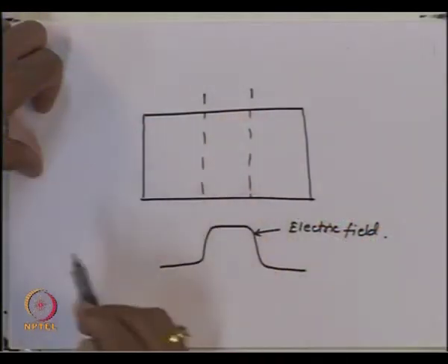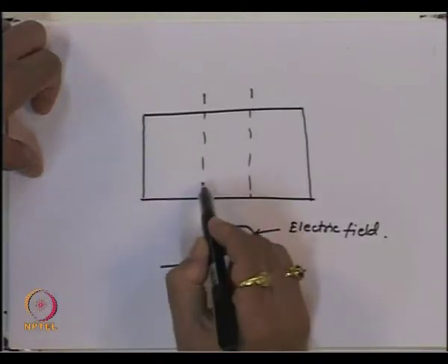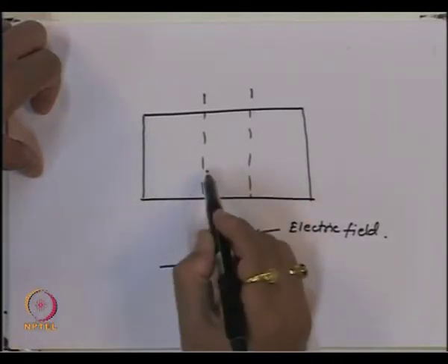So, now we have to modify our simple PN junction in such a fashion that firstly we have the constant electric field region as wide as 10 to 20 microns, and then only you can have the contribution of the drift current increased, and also this length should be reduced, so that the photon when it is incident, practically it gets absorbed into this region, which is this depletion region.